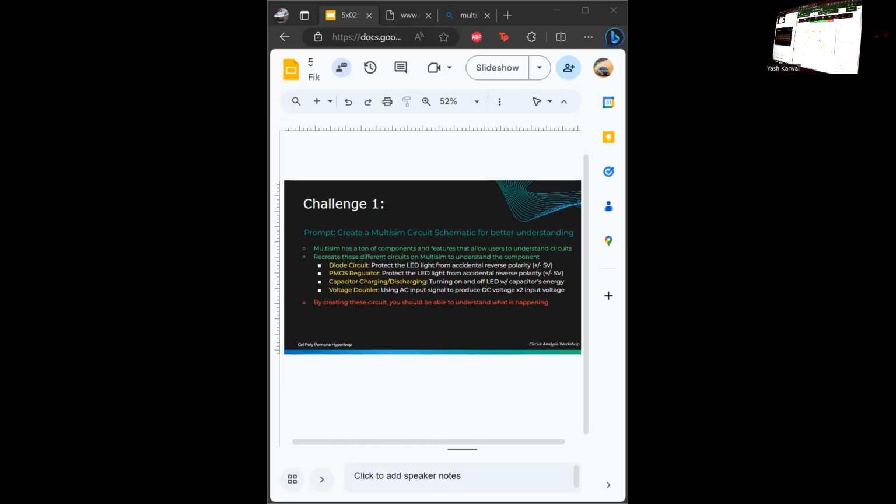If VGS is higher than a certain amount, then it turns off for PMOS. VGS is the difference between here. Yeah. So generally on a data sheet for a specific PMOS, there are a bunch of different PMOS for a bunch of different applications. You can have power PMOS, you can have small signal PMOS, and they'll have different VGSs. The way I choose them at least, I look at the VGS, say I want a logic PMOS or NMOS. And then I make sure the VGS is above what my logic level is. Basically, let's say VGS is 2.7 volts. And I can use it for a circuit because any voltage above 2.7 is going to turn on or off. At least in my opinion, that's a better way of looking at it.